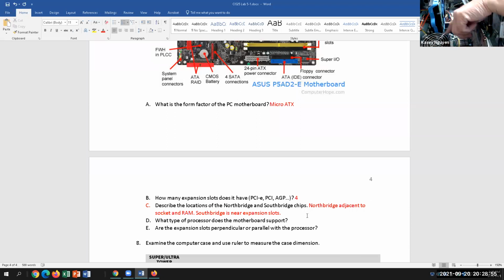So to remove this, you would have to unmount the screws for your heat sink. Okay, and then you would need to lift this up, and then there's a zip, which is a little lever. You can flip it up, and then the processor will unmount. You have Intel? It just says Intel, right? Yeah, when you remove it, you would just see it as Intel.